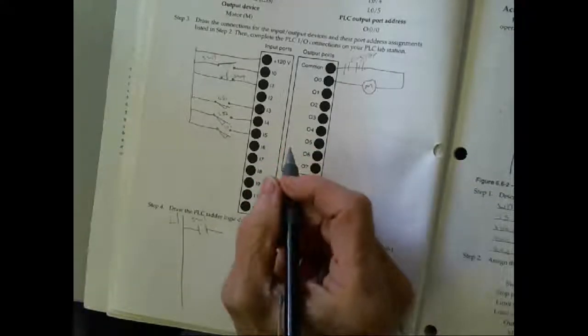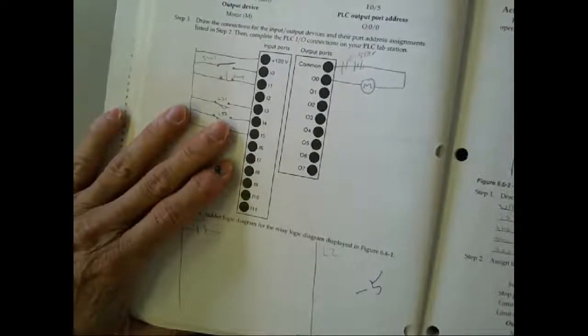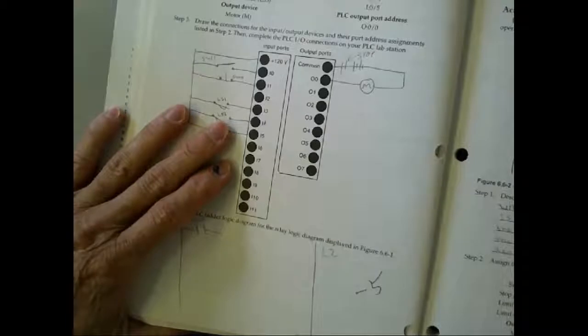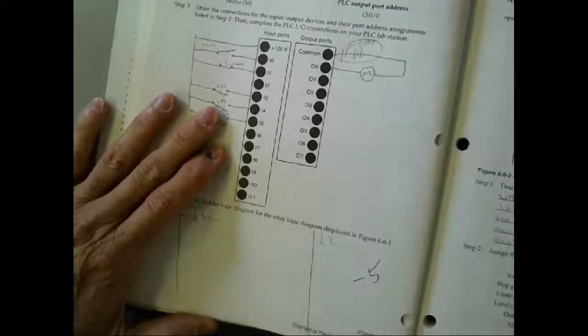Now, we might make some decisions inside our PLC program, like stop the program from running. So we might have an E-stop contact inside the PLC program, and that would be an examine if open. But we would also have this circuit right here that would disconnect power from all your outputs.